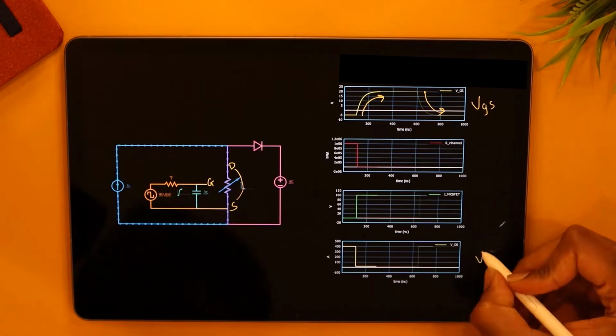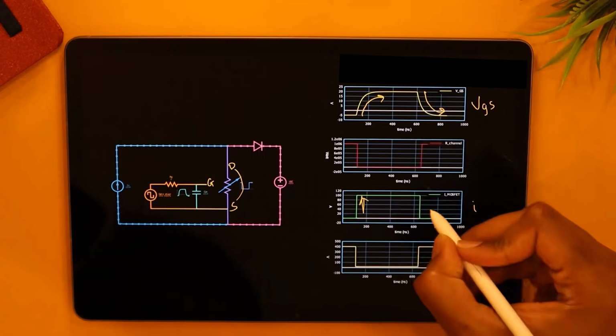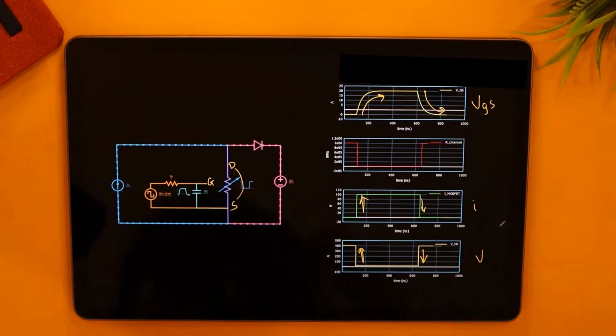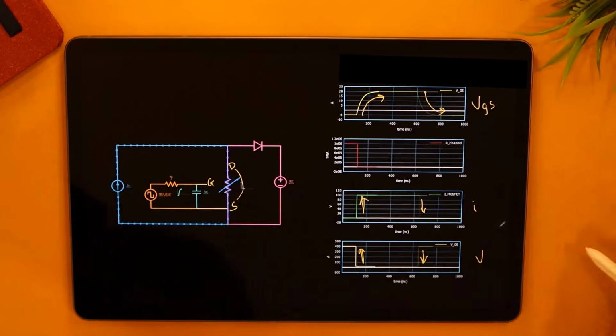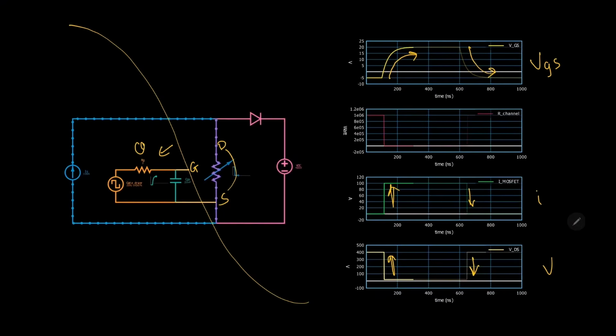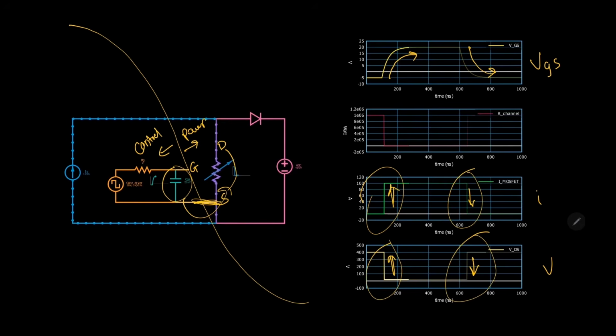And by the way, look at the voltage and the current waveforms across the MOSFET. They are pretty much still ideal. So whatever we have done has not affected the power side of things. And it makes sense. I mean, look at this circuit here. On the left side, you have the control, which is controlling the switch state. On the right side, you have the power stage. And they are pretty much disconnected from each other, isn't it? This electrical circuit is not really connected. There's only one single wire here, but there's no return path. So I don't expect this to have any impact on the power side. That's why you see all the instantaneous transitions still. So CGS doesn't quite do it.